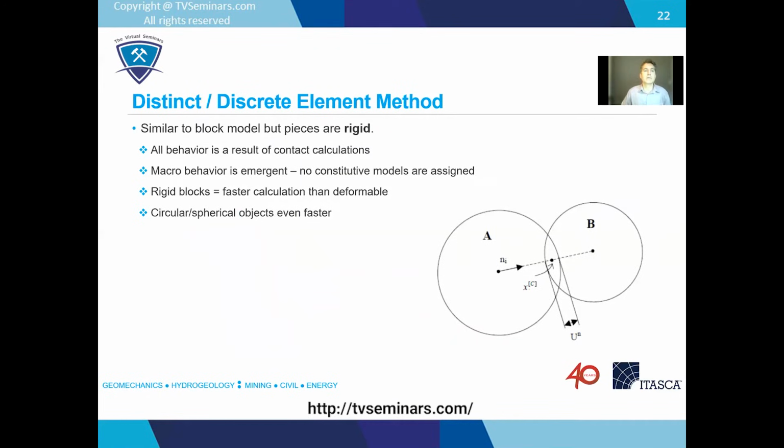So again, similar to the block model, but the pieces now cannot deform. And what this means is that it's much more efficient computationally. We're only looking at deformation of contacts. We don't have to do the stress strain calculations for the pieces. It can theoretically run a lot faster, especially if you consider the pieces to be spherical, then the contact calculations become very simple.